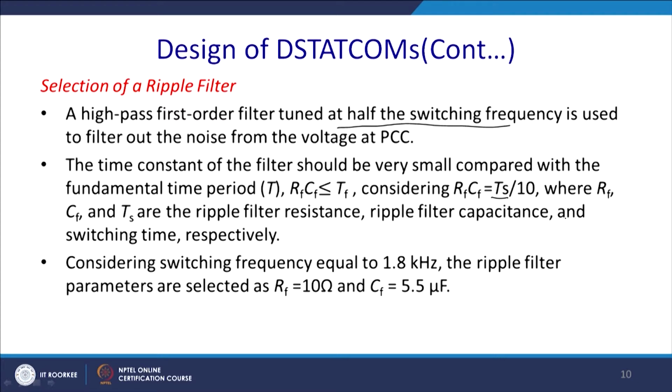So, we have already chosen that the switching frequency of this inverter is operating at 1.8 kilohertz. So, thus the parameters are selected to be Rf equal to 10 ohm and Cf equal to 5 microfarad. So, this is the case.